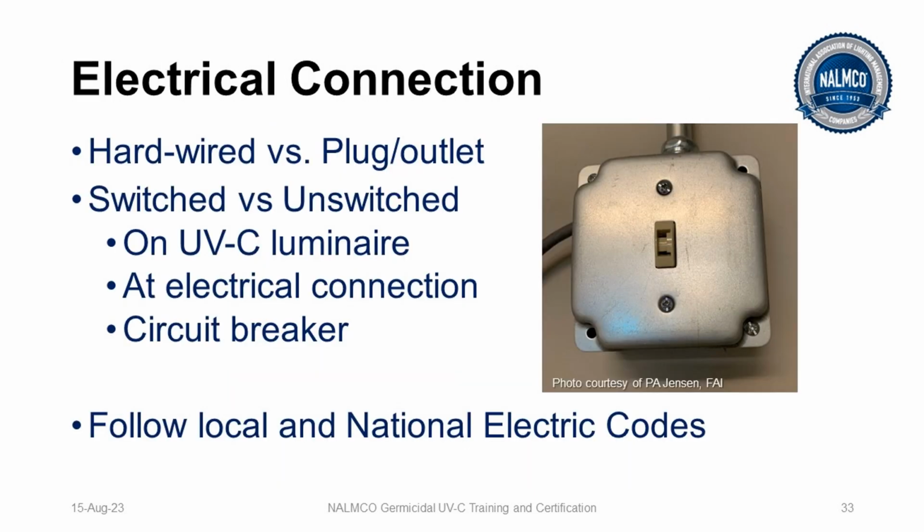Electrical connection must be decided as part of the design development. Are the fixtures going to be hardwired, or are they going to be plug-in outlet? Will that outlet be switched or unswitched? Will it be switched at the location, which in this case is a keyed switch? Will it be at the breaker box or somewhere in between? And obviously we have to follow local and national electric codes.